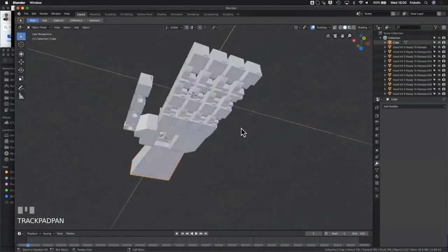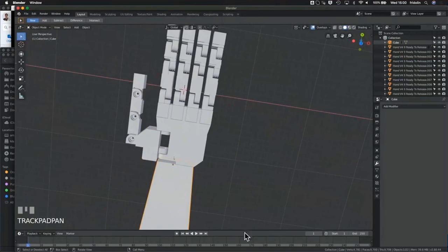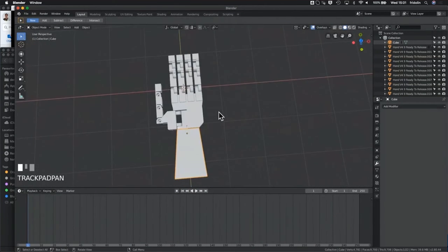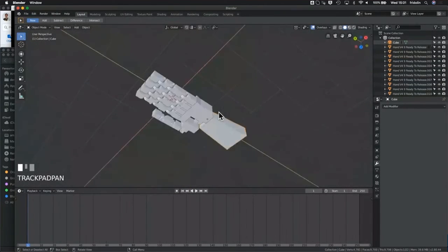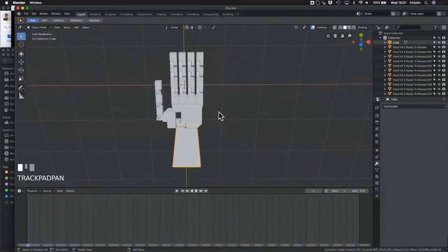So now if we wanted to animate this, this is where we use Blender's timeline features. I want to talk about animating. I don't think we'll have time to work through all of these examples, but I want to at least demonstrate them to you. So if I wanted to animate the tip of this finger, then we use the timeline down here. If I press the play button, we can see that now we're moving through time along there. If I click at a certain point along the timeline, we go to there, and I can type in a particular frame over here.